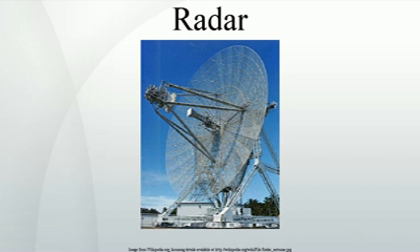Doppler measurement is reliable only if the sampling rate exceeds the Nyquist frequency for the frequency shift produced by radial motion. As an example, Doppler weather radar with a pulse rate of 2 kHz and transmit frequency of 1 GHz can reliably measure weather up to 150 meters per second, 330 mph, but cannot reliably determine radial velocity of aircraft moving 1000 meters per second, 3300 mph.